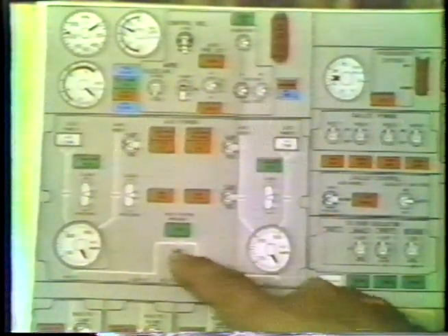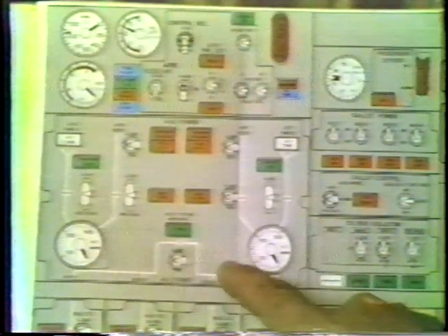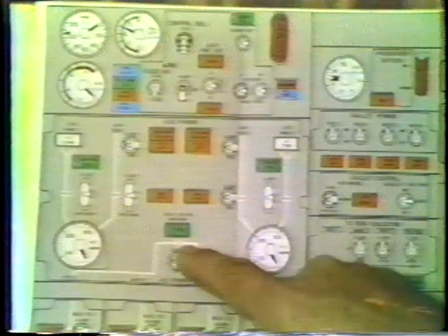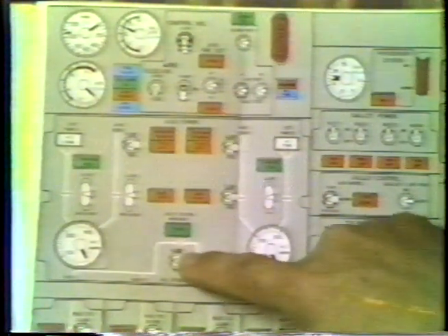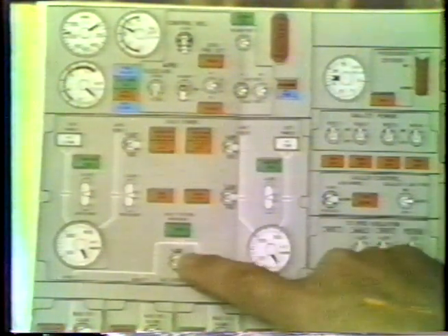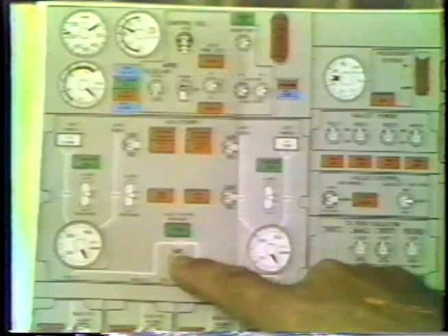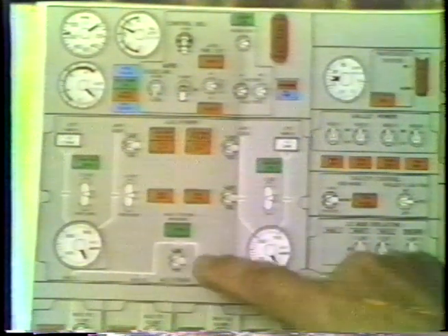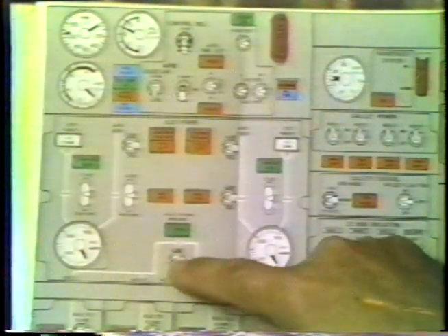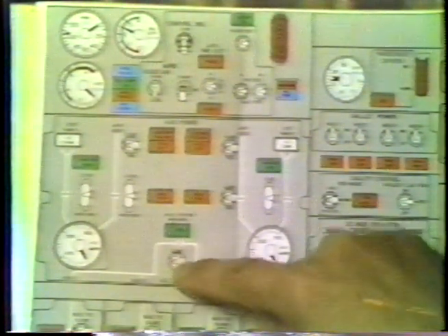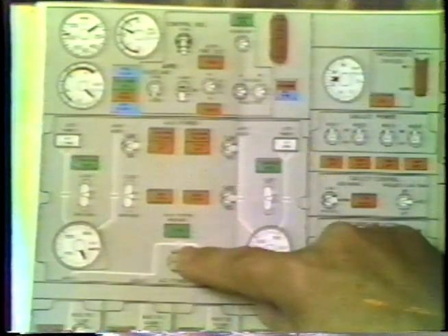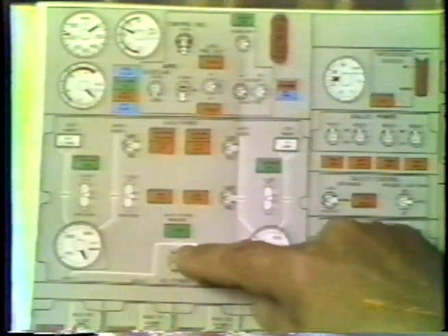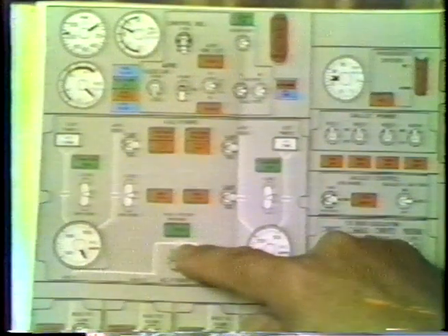The split system breaker is a very unique item, and it has many automatic functions to trip, but it has no functions that will make it automatically closed. If you want the split system breaker closed, the operator must move the switch to close. Now, when he moves it to close, it may or may not close, depending on whether conditions are correct.